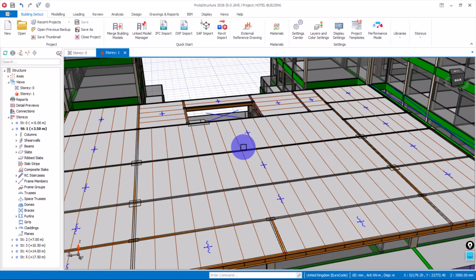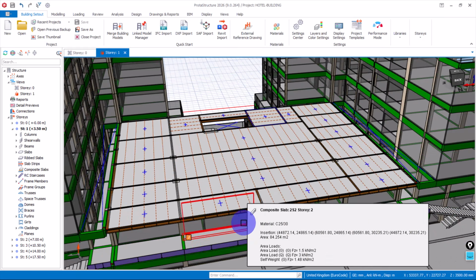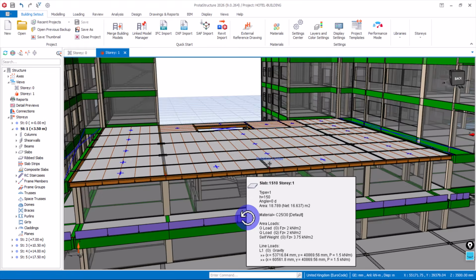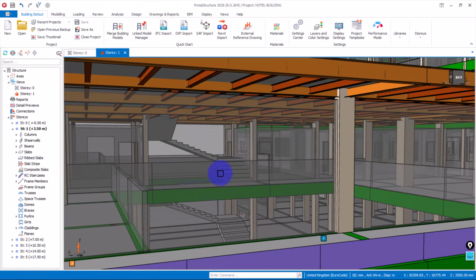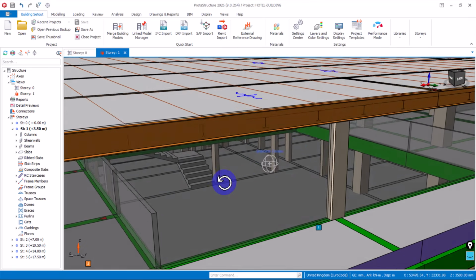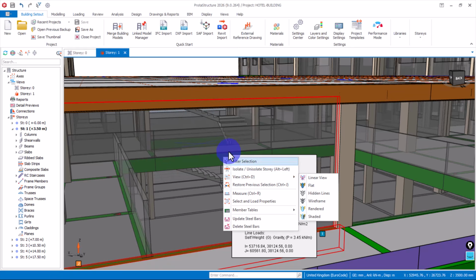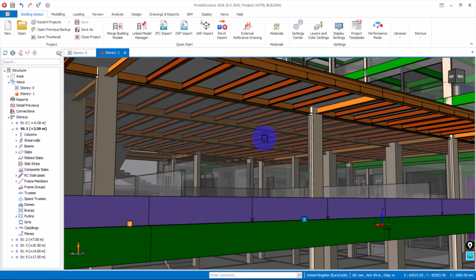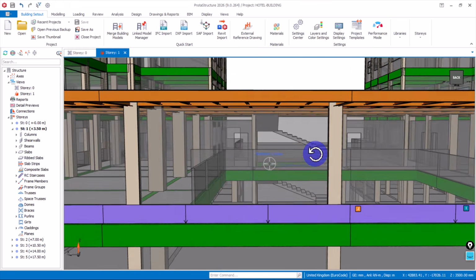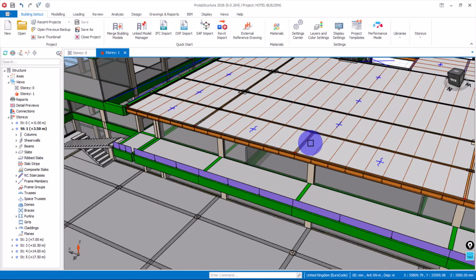This particular rooftop is to be used as a restaurant, and below it they don't want columns to appear, because below it is a void from the ground floor down to this very area. So we cannot use concrete beams for this kind of span, which is 15 point something meters. That was how we came to propose a composite member,